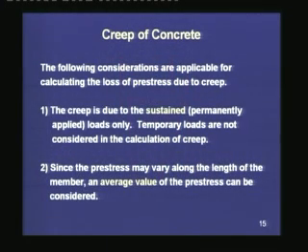Now, when we are doing this calculation of loss in prestress, the following considerations are applicable. First, the creep is due to the sustained loads only. The sustained loads mean the permanent loads. Temporary loads are not considered in the calculation of creep. Usually, the dead load, which includes the self weight, is a permanent load, and a fraction of the live load may be permanent, like the furniture and the bookshelves in a library, which can be considered a sustained load.